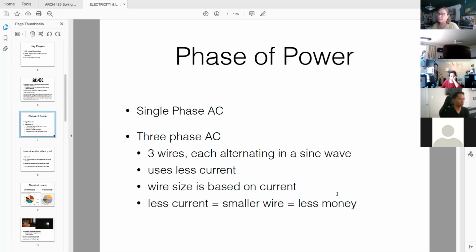And what the effect of that is that the size of most mechanical HVAC units that go onto a residential project are designed to be single phase, and they will max out at about a 5-ton capacity. Because if you think about it, majority of residences are 2,000-3,000 square feet max, or a lot smaller. They're not giant buildings. The heating and cooling loads are a lot smaller. Therefore, a 5-ton unit is a reasonable size.